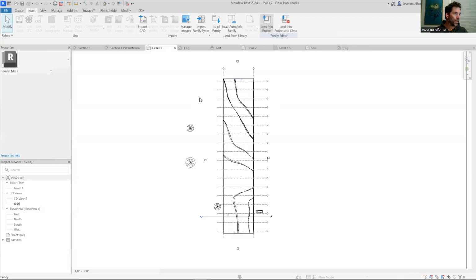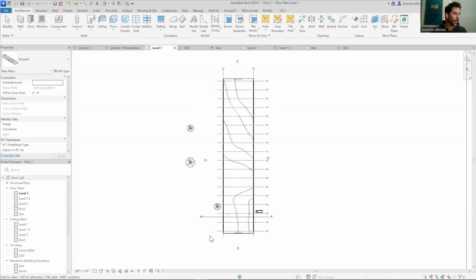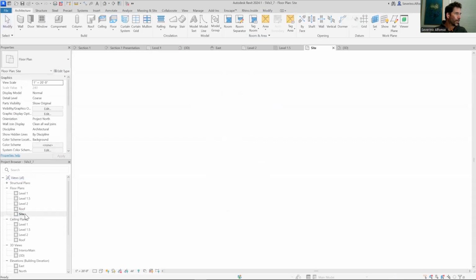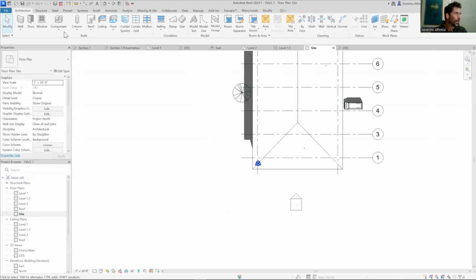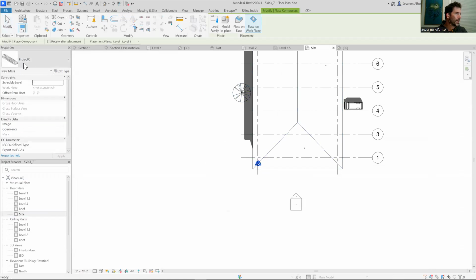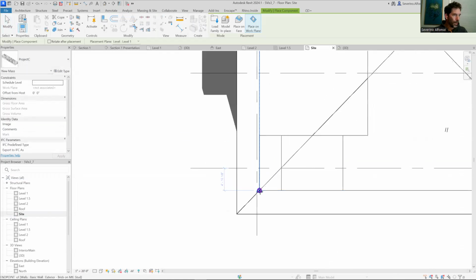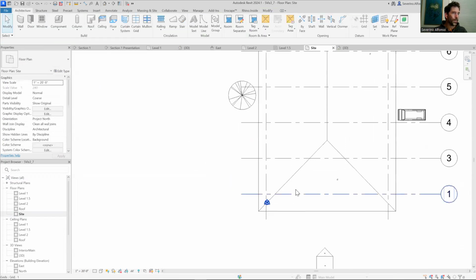It opens up the project, wants to place it, but again, we escape, we go to the side view, because that's where we can find the origin point. We click on this one, it brings the latest time we loaded. So click on the endpoint there, which is the origin point, escape.